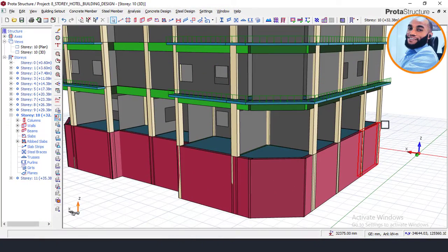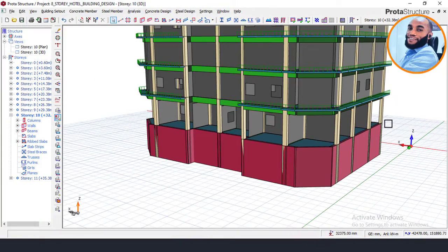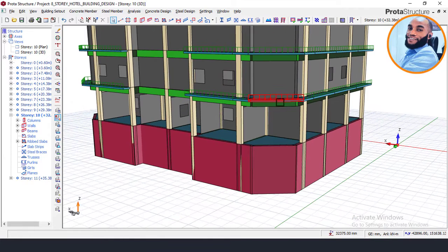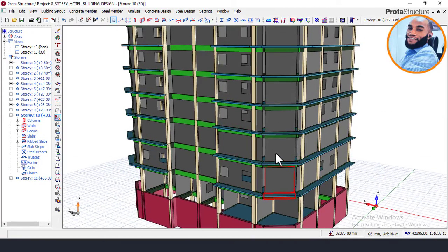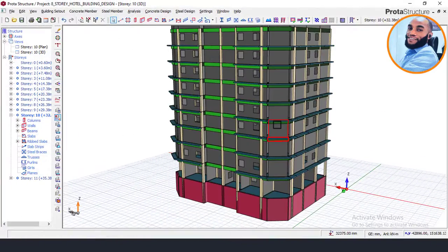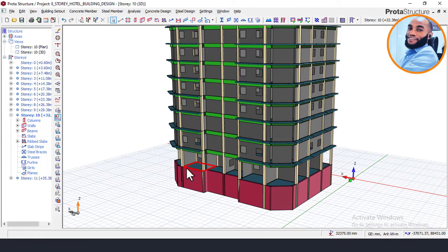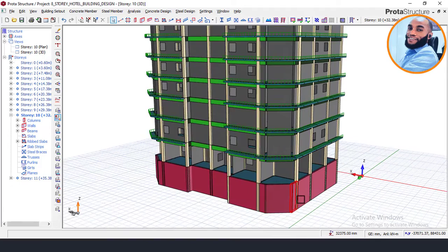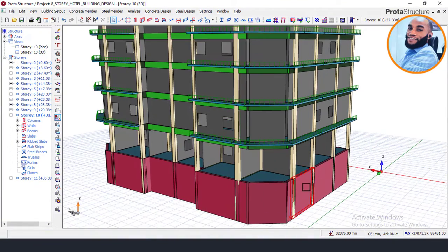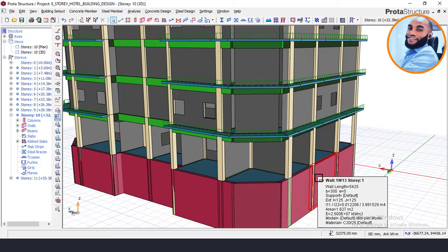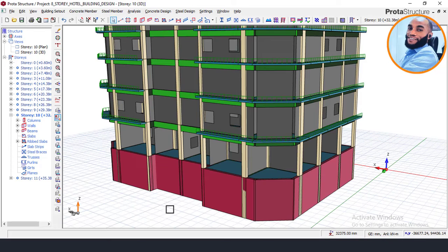Now, when I say short time, the disturbance might be during the construction of the project. When they are performing the construction, there might be some vehicles passing through the surroundings where the earth is being retained. In that course, the load from that vehicle will also have an impact on the basement wall or on the retaining wall, because the retained soil is being disturbed by the load.